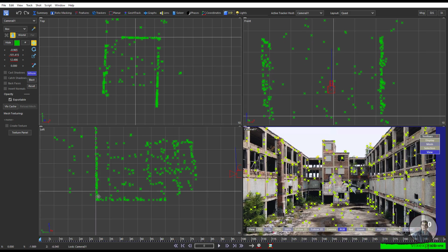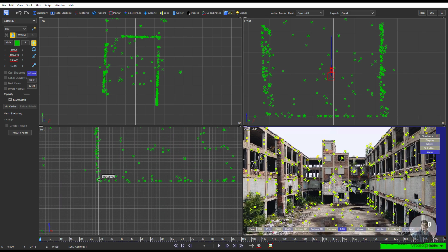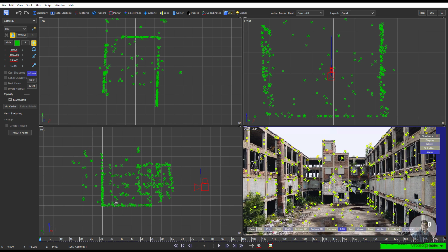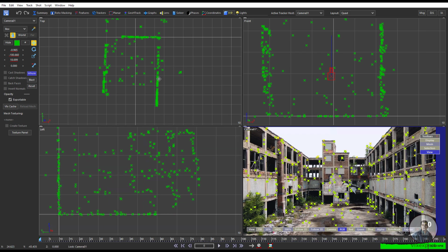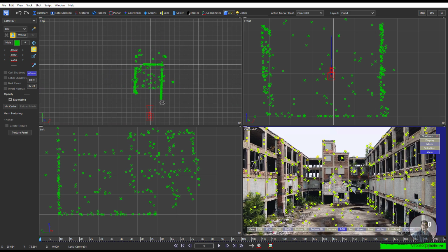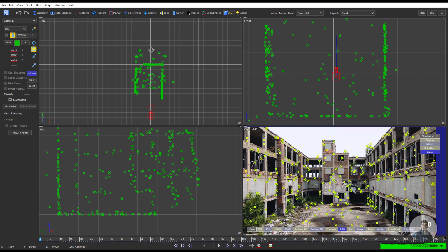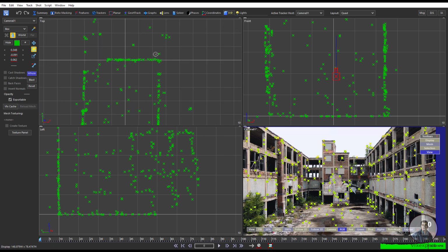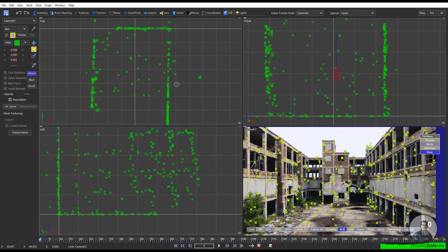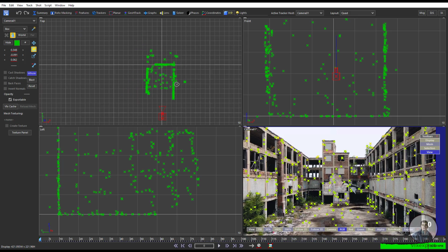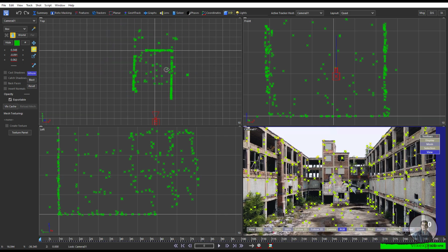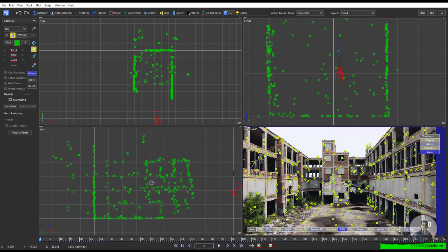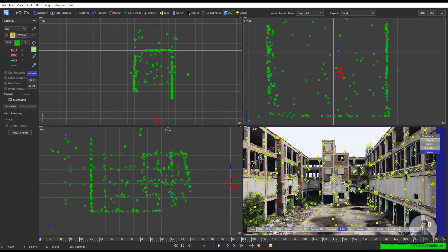Then easily we can move. As you can see this one here. Even if there is any requirement for rotation, then you can also take this rotation tool and adjust. So maybe I am going to adjust a little bit. You can see here. Then middle mouse button scroll, then you can zoom in, zoom out. Hold the middle mouse button, then you can pan. So maybe I think this is sufficient, and the remaining things you can adjust according to your requirements here.